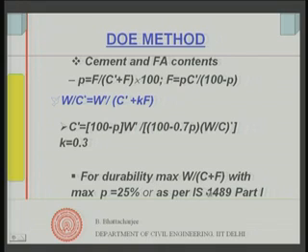but at the moment IS 1489 part 1 allows P equals 0.25, and therefore the F that you can take should correspond to P equals 0.25 only in this calculation. That is the stipulation or recommendation of the Indian Standard Code.